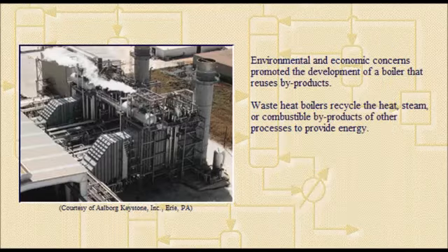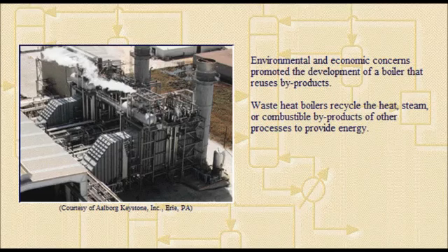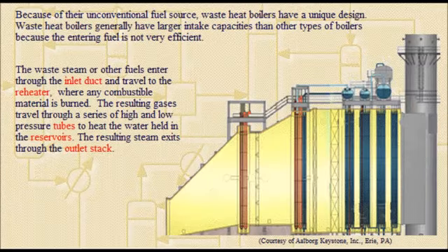Environmental and economic concerns promoted the development of a boiler that uses byproducts. Waste heat boilers recycle the heat, steam, or combustible byproducts of other processes to provide energy. Because of their unconventional fuel source, waste heat boilers have a unique design. Waste heat boilers generally have larger intake capacities than other types of boilers, because the entering fuel is not very